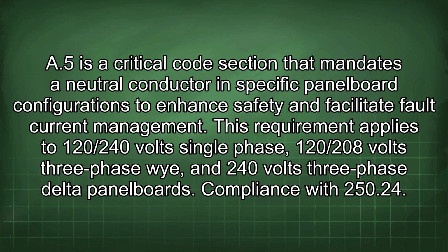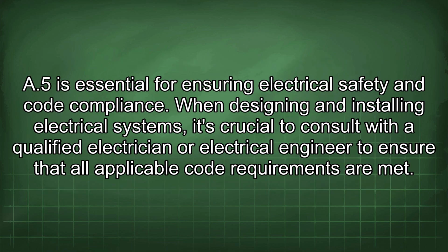This requirement applies to 120/240 volts single phase, 120/208 volts three-phase Y, and 240 volts three-phase delta panel boards. Compliance with 250.24(A)(5) is essential for ensuring electrical safety and code compliance.